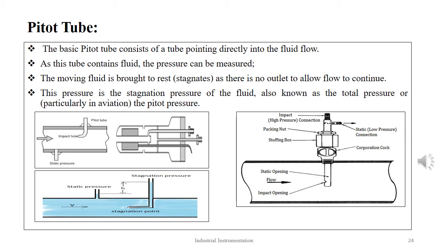The Pitot tube is also used to determine the velocity profile in a pipe, and this is done by measuring points at various distances from the pipe wall to construct a velocity profile. The Pitot tube is a primary device and it has the advantage over an orifice of practically no pressure drop. Its usefulness is limited to clean gases and liquids only, as the sensing element is a very small orifice.